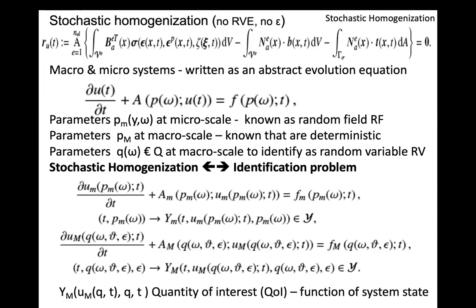So for example, for finite element and homogenization, which is already used, you're basically talking about internal energy. And the finite element model is a discretization method which gives you the best approximation property in terms of internal energy. And if you talk about the dissipated internal energy, that's called dissipation, you can extend this validity, that this is the best discrete approximation, to something like plasticity, damage and so on, which is already not so bad. So if I take this in the spirit of classical homogenization, I'm getting energy, dissipated energy, in terms of both of these models,